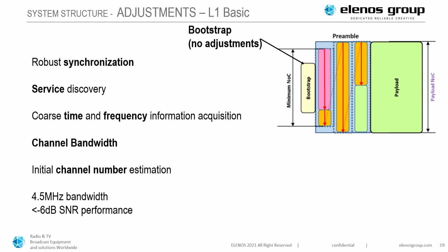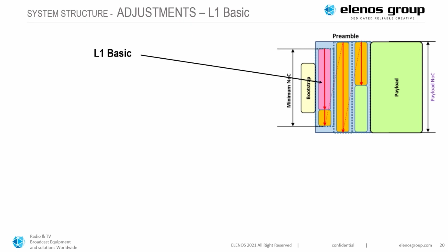The first item is the bootstrap. As I mentioned, this is a fixed set of data. The data is organized, again, very basic information to literally wake up your receiver to tell you, I'm getting channel 26, it has 4 programs, it's OFDM modulation, et cetera, et cetera. So that just gets the TV going.